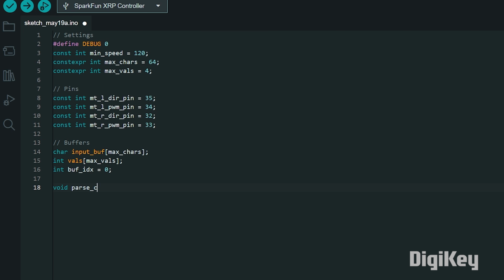It's up to you how you want to send information over the serial line. As I've mentioned before, you could use SPI or I2C, so you could set up your microcontroller to be a client that attaches to a bus. But for our project, a very simple serial over USB gets the job done. What we're going to do is send the values over the serial line. They are going to be comma-separated values, so a comma between each one, and then each line will end with a new line character. That's how we know that the whole message has been sent.